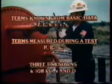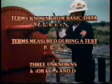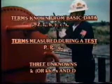This leaves us with 3 unknowns: permeability K, or KH if H is not known, skin factor S, and non-Darcy flow coefficient D. Now we must see how the values of K, S, and D are determined. Let's start with the easiest, K.